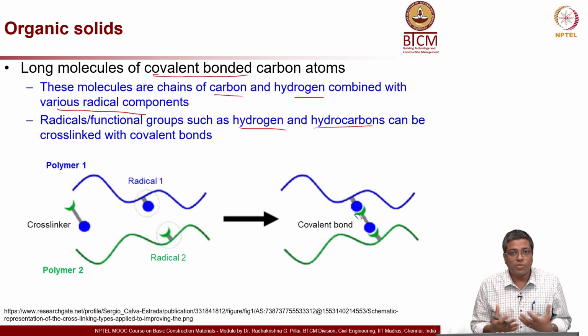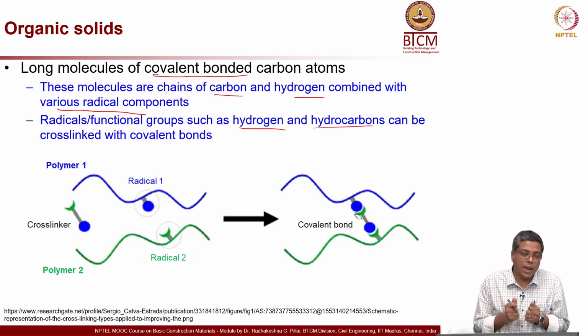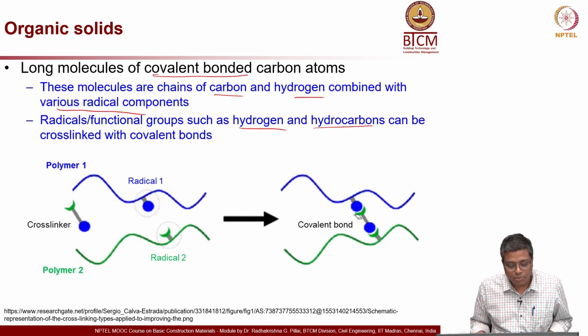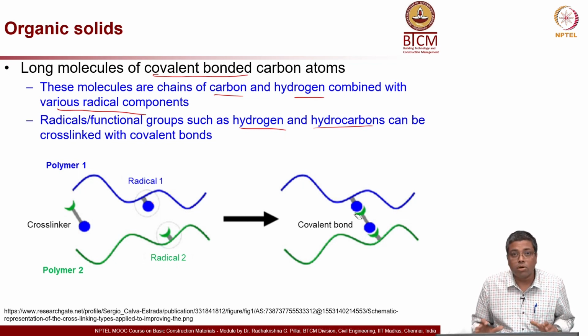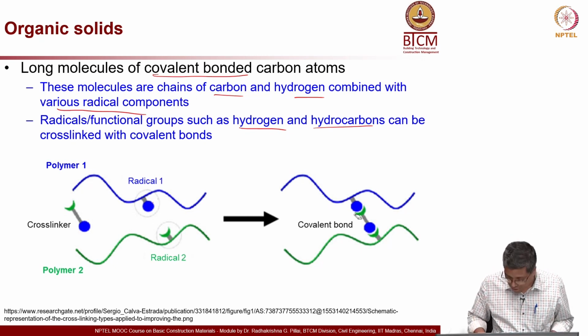Even in some of the advertisements you can hear, when you talk about paint, cross linking polymers are used in paint. That helps in preventing cracking of the paint. So, on the wall surface you will not see much cracking, because they have these cross linking polymers, which change their elastic behavior a little bit, so it takes more deformation for the paint to crack.